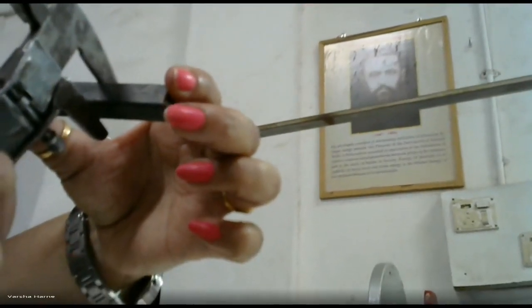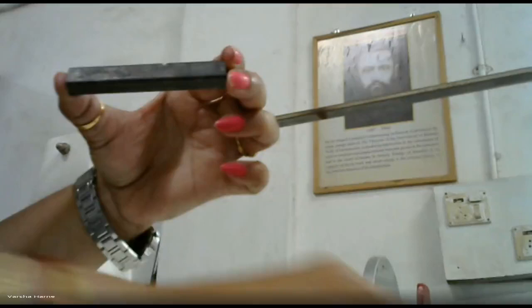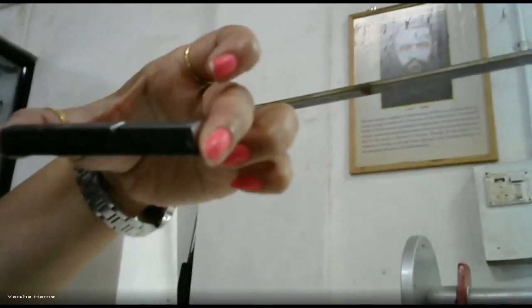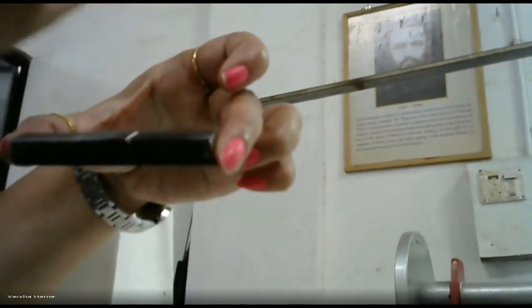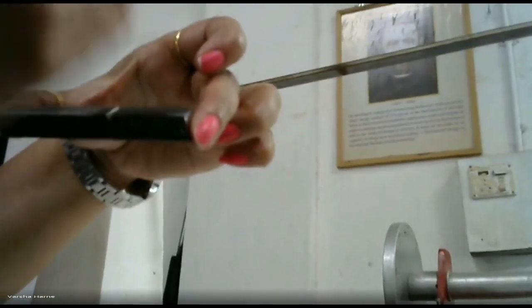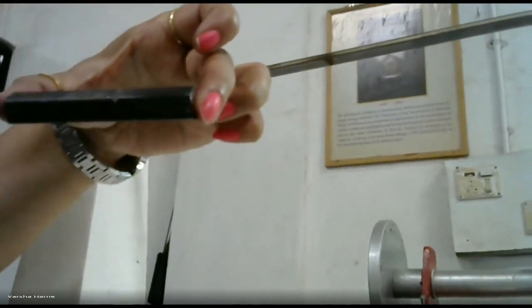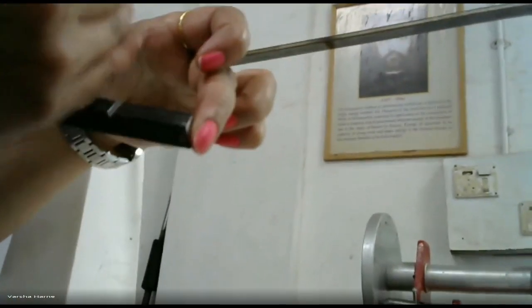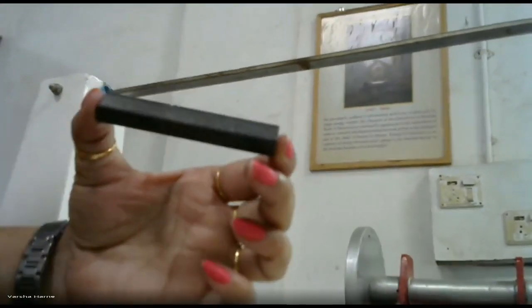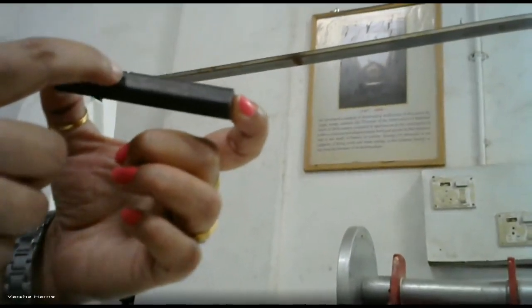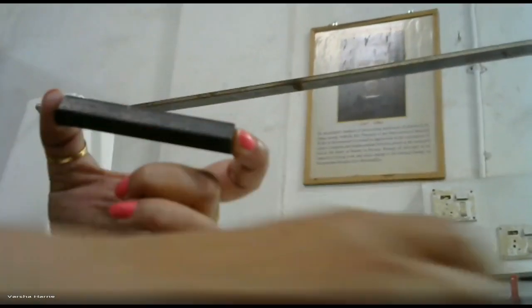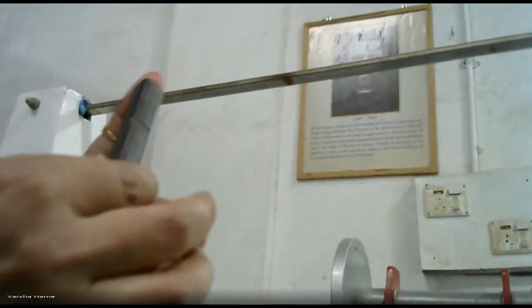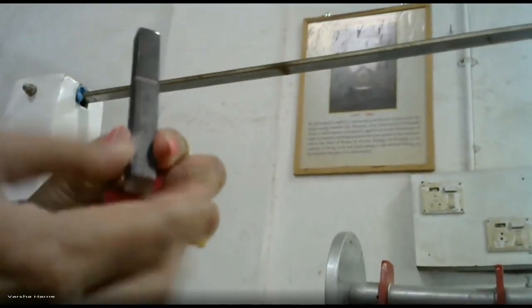The notch criteria is very important here, because whatever hammer we apply, the position of the hammer, which is exactly one critical point, is where the hammer is suddenly applied. That's why we require the notch. And according to that, in the Izod and Charpy impact, if you see, the notch is a V notch here and a U notch there. So that's why the position of your beam will be like that, and the hammer is applied here, isn't it?